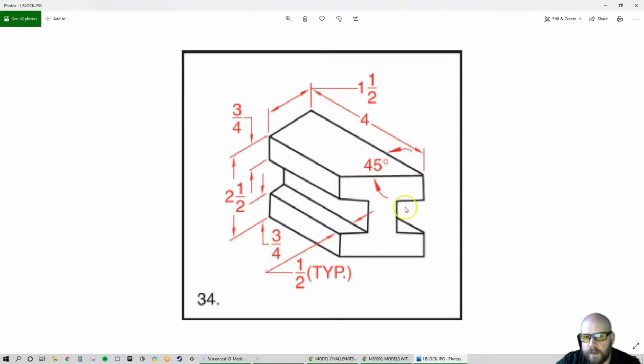What I'm going to do is, because this looks a lot like an I-beam to me that has kind of a cut at the end, make it the way that I think somebody would actually make this thing, but keeping in mind I want to reduce features. So I'm going to try and sketch my first sketch as one of the most detailed sketches. If we look from the side, an I-beam looks like an eye like this. But we're not going to be able to put this slant in right away, and you'll see what I mean in 1 second.